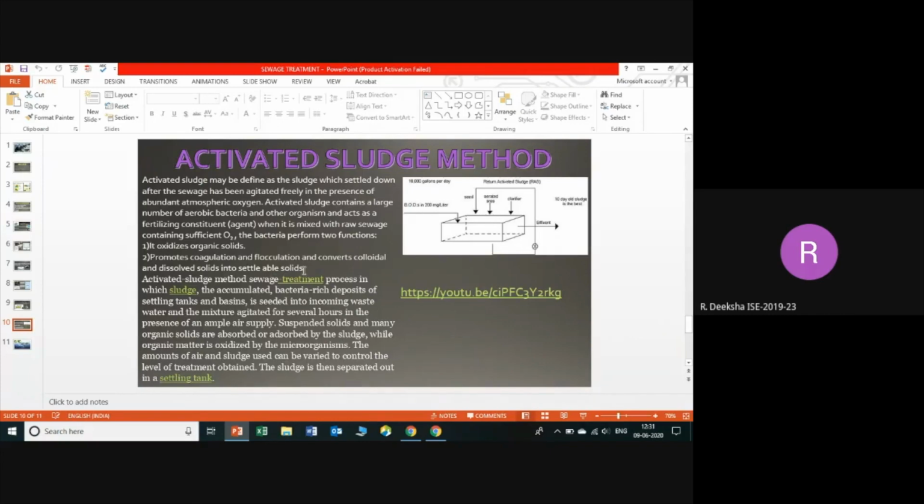So the activated sludge process involves extensive aeration of sewage water and the process of aerobic oxidation being enhanced by the addition of a part of sludge from the previous oxidation process into sewage water. The added sludge from the previous oxidation batch is known as activated sludge, since it contains a large number of aerobic bacteria and other microorganisms.